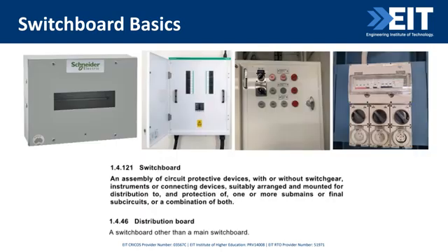Here we've got a couple of pictures of some different types of switchboards. This could be what's described as a panel board or a little load center because it's fairly small. Here you can see a switchboard with its main isolator as well as your chassis, which contains all of your little circuit breakers. This one shows a switchboard with some indicator lights. And over here we have again a little single chassis, or a little 18-pole panel board or load center, with some power points hanging off it.